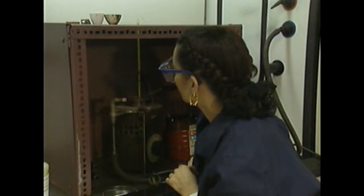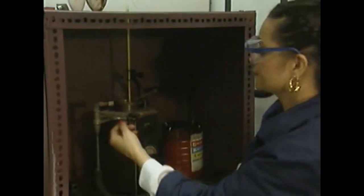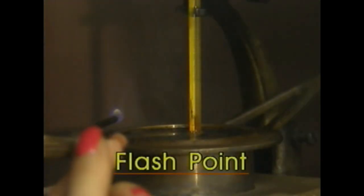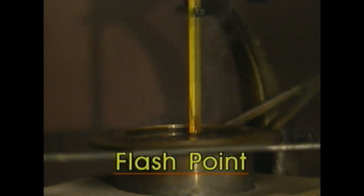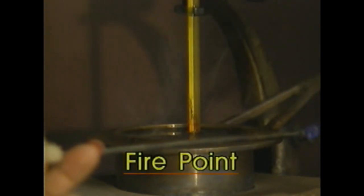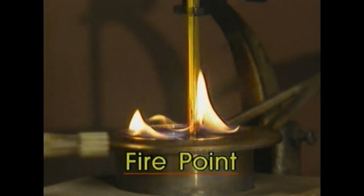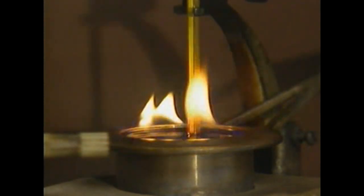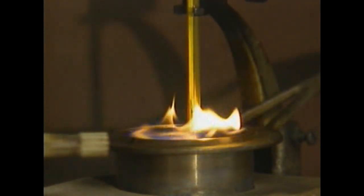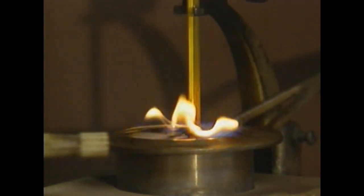Two other temperature-related properties of lubricants are flash point and fire point. The flash point of a lubricant is the lowest temperature at which the lubricant's vapor will ignite when it's exposed to a source of ignition. The fire point is the lowest temperature at which the lubricant will burn steadily when it's exposed to a source of ignition. This occurs because enough vapor is created to cause continuous burning. If either the flash point or the fire point is exceeded, a fire hazard exists.